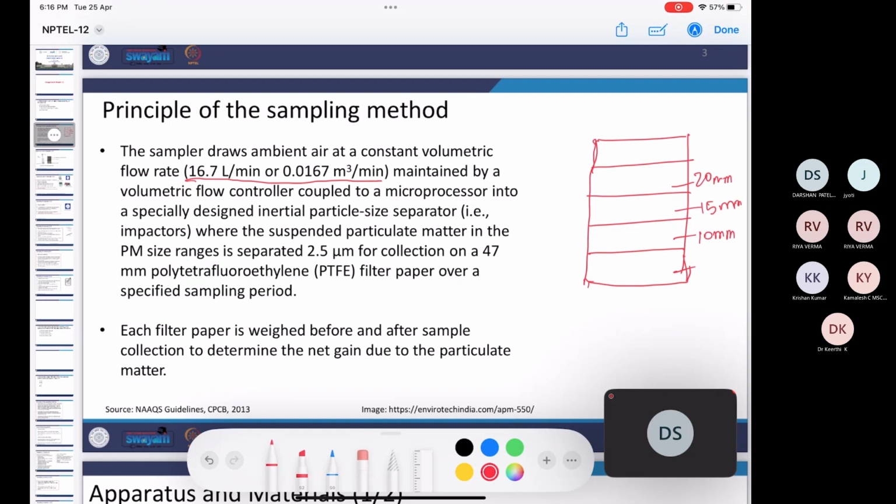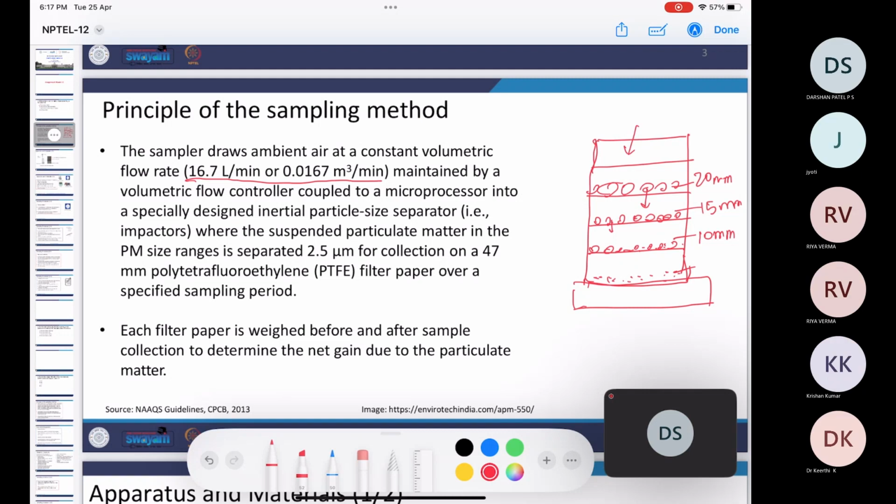So what we did was we just put the sample in here, and this sieve was placed on a shaker, and whatever the size, in this way the size segregation was done. Like the 20 mm aggregates would stick on this sieve, smaller size would get trapped on this sieve, and 10 mm would get trapped on this sieve, and the finer ones will move downwards. So this was the sieve analysis that we did, and this is your basic gravimetric method.